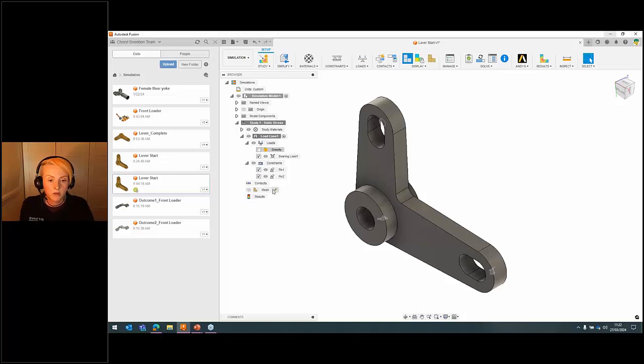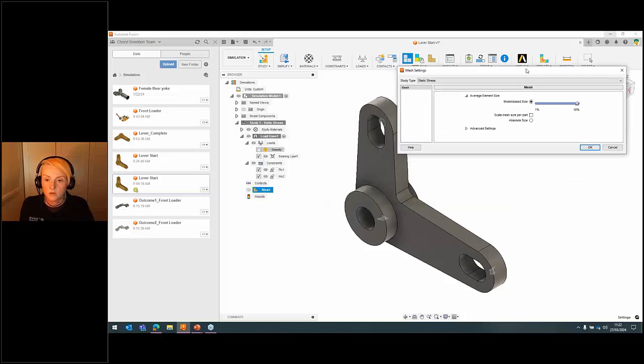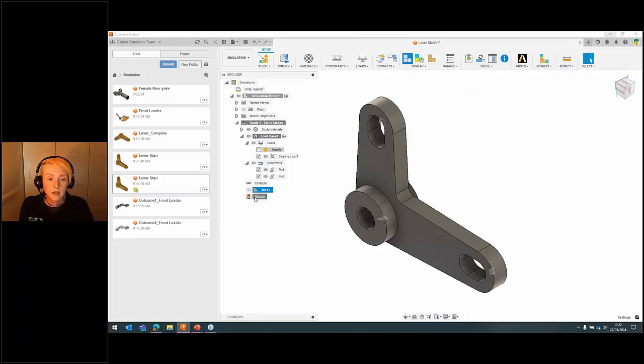Now that we've done that, the one thing that we still need to work with within the software is the mesh. There are various different settings for the mesh. Today we're going to go for an absolute 0, which means that we can say that our element sizes are within a range. There are other ways to work with the elements, and if you've got any questions around this afterwards, then we can help you to understand it a bit more. So I'm going to change the size of my mesh control to 2.5 millimeters. And then for this example, I'm just going to run the load case